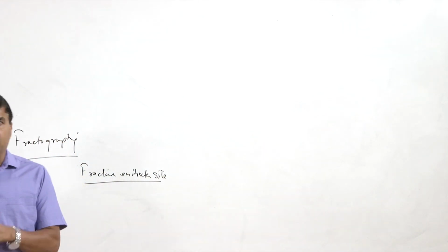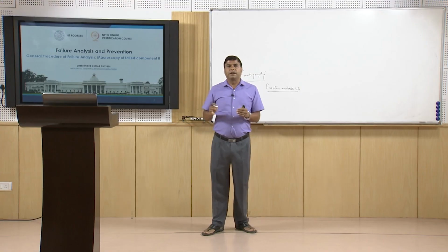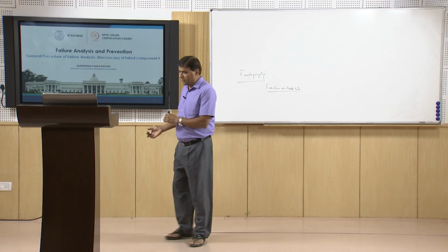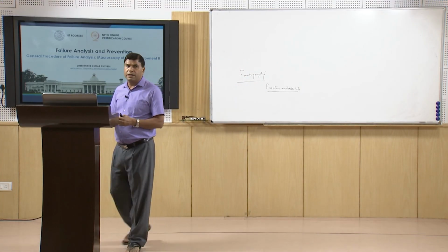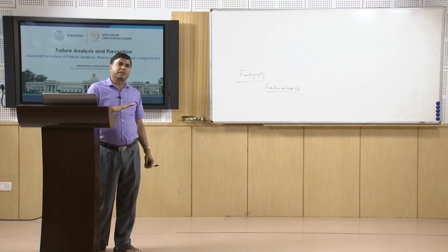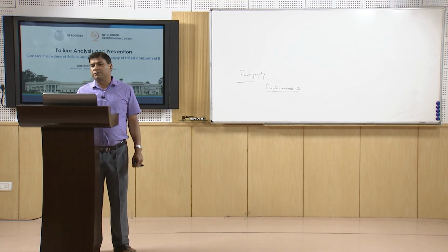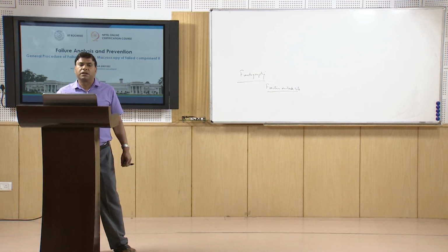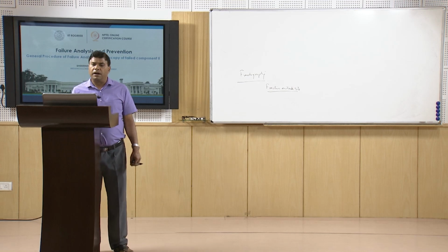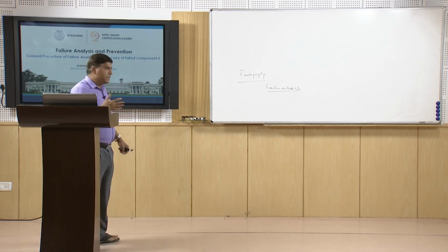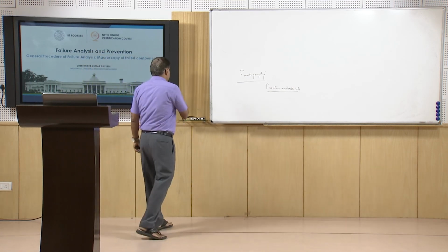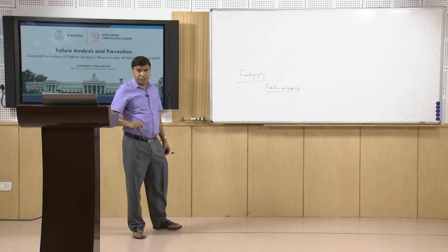The nicks and gouges are two typical features, and the ratchets are other ones which indicate the location where fracture initiates. That gives an entirely different kind of fracture morphology, texture, zone, and color, and that is why it is comparatively easy to identify the location where fracture has initiated.